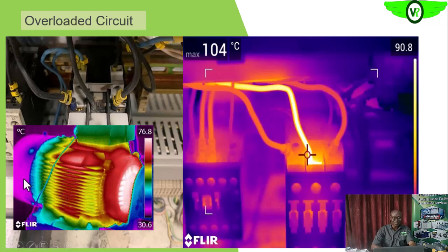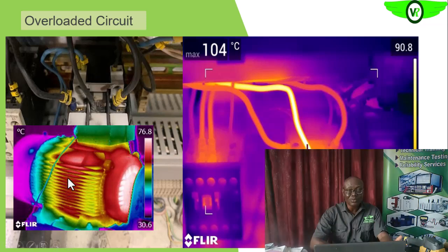So now what is left for you? During normal operations, when there are no issues with the electric motor, you will take this thermogram and use it to form your baseline data that you will subsequently be referencing. So you take the spot temperature at the middle, which gives you an idea of what is happening in the winding. Let's assume that the spot temperature is around here, about 60 something degrees Celsius. Once you put on the camera, you move your cursor to this point, and it will give you the temperature of that spot. Are you getting it? Then you see the cooling effect of the fan very clearly. You can also go ahead to get the temperature of those spots. Then around the bearing housing, you get the temperature also.